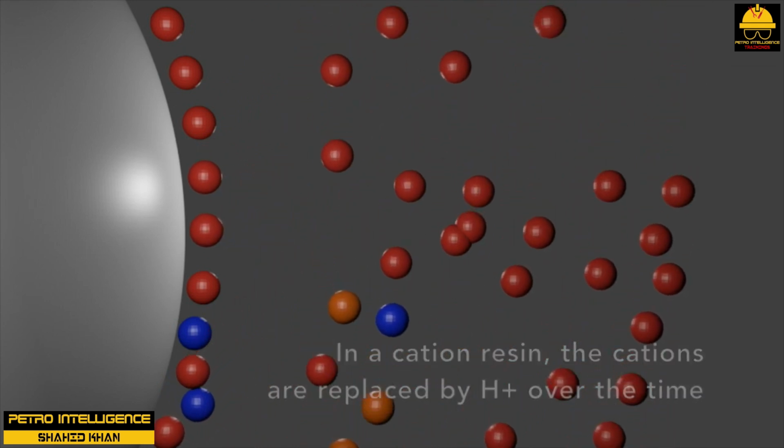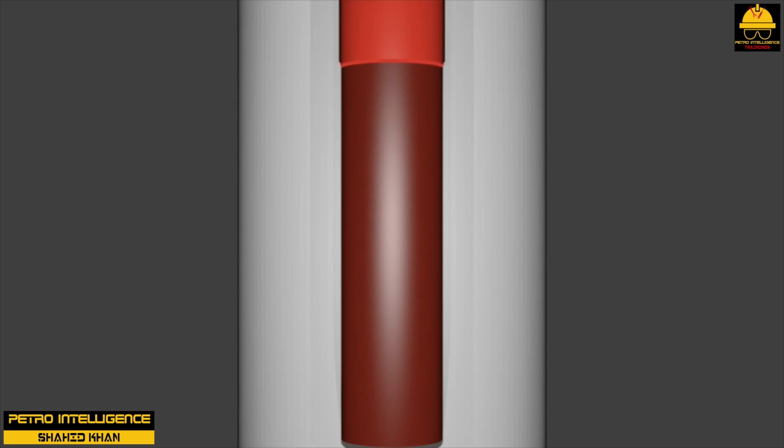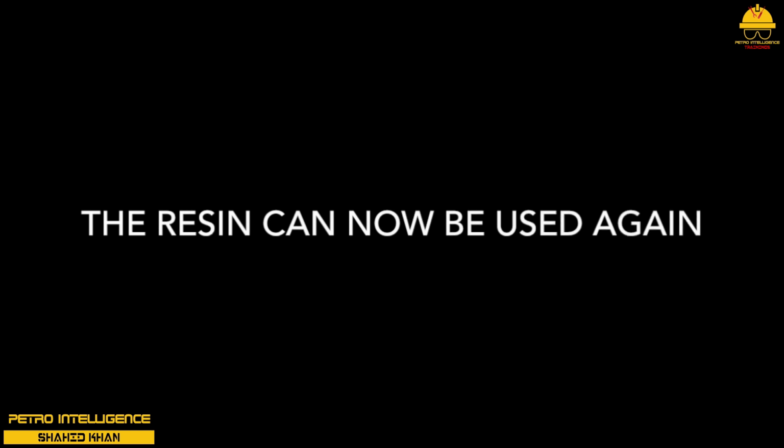Depending upon the use for which it is intended, an ion exchange resin may have any one of a number of different ions active on its surface. Hydrogen ions are commonly used in chemical processes. Obviously, over a period of time, all of the ions available on the surface of the resin will have been exchanged, and no further exchange will be possible. At this point, the bed is said to be saturated, and it must be regenerated before it can be useful again. Regeneration is the restoring of the original ion to the surface of the resin beads. In the case of the water treatment resins, the bed could be soaked in a concentrated solution of sodium chloride, replacing the hard metallic ions with fresh sodium ions.